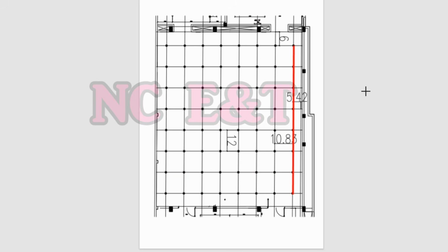You can see, from the remote area we have transferred the same information to our project. We have made the construction lines, and we have mentioned that during drawing this construction line we use the distance between two sprinklers on the same branch 12 feet, and the distance between two sprinklers between the adjacent branch 10.83.